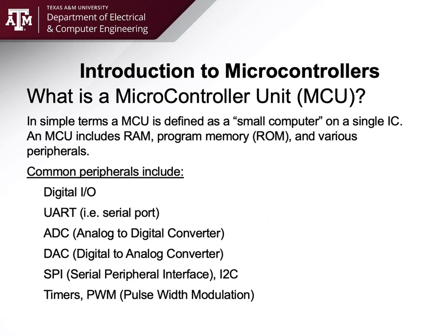Then there are some general purpose interfaces for communicating from chip to chip. Like I was talking about a moment ago, with the basics of a microcontroller processor, you usually have other peripherals you would hang off of the processor, for instance additional A to D converters, more precise ones, or ones doing some specialized function such as a touch sensor interface or humidity sensor. You can get specialized ICs that do a specific task, and you would want to communicate that data digitally, but you don't want to use a bunch of I/O pins to do it.